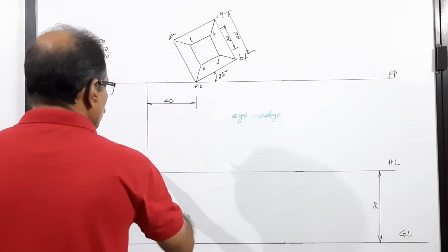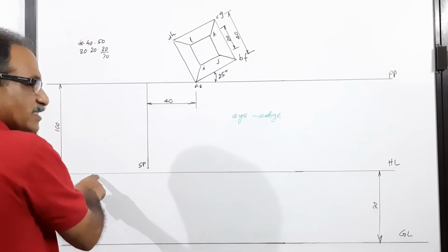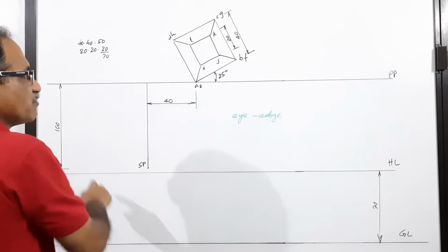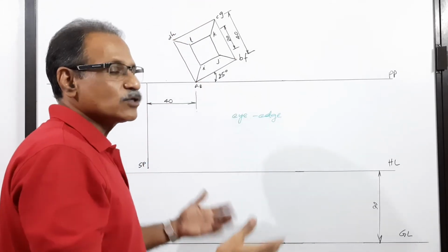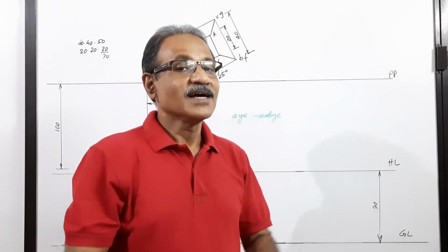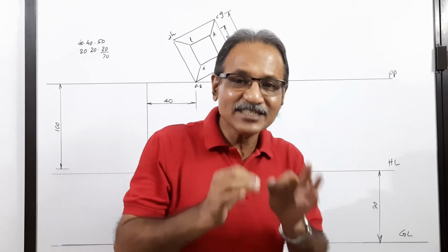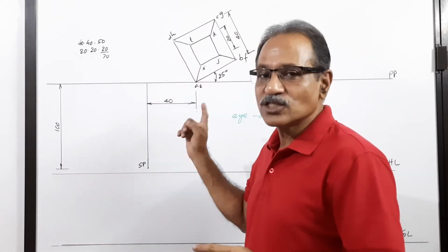For that, you draw a line through SP parallel to AD. You get V2 here; drop it down to HL and you get capital V2. Capital V2 is the vanishing point of all lines parallel to AD. By using those two vanishing points you can draw. However, in this case the easiest method is to draw this using a single vanishing point.